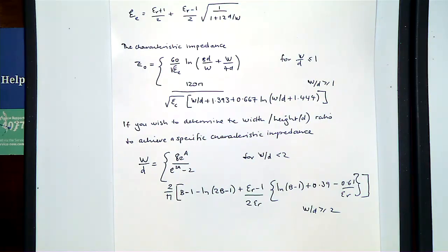So under those circumstances, the only thing that you've got available to you is to modify the width of the actual conductor. And even then, there are some restrictions, right? I don't know if you've actually gone through the process of designing a PCB or a chip, but usually you can only design the metals or the conductors to certain widths and certain thicknesses.